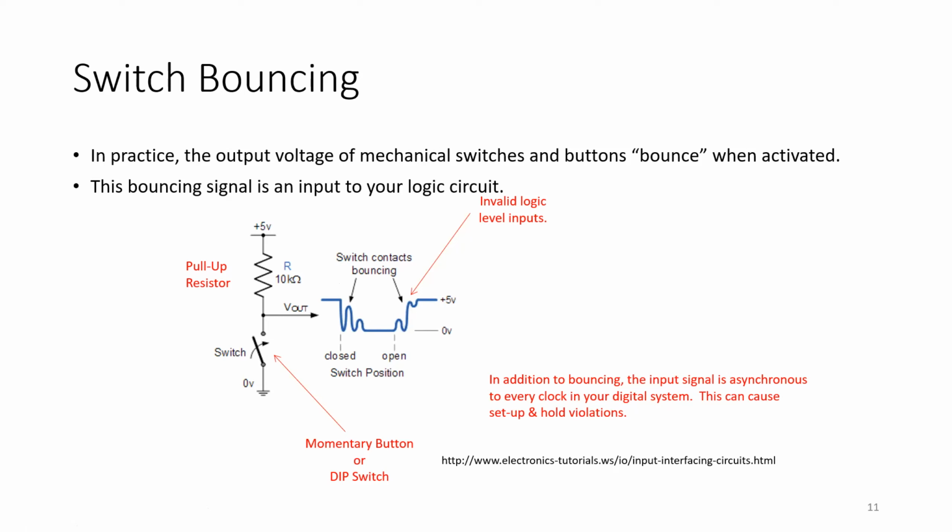And as I said, it depends on the switch. You may get a switch with very strong spring that may make many oscillations. So the spring itself dictates 10 or 20 or 30 milliseconds, just to make sure it is quite stable. But for our applications and with our just simple switches, 10 milliseconds will be more than enough. Any more questions?